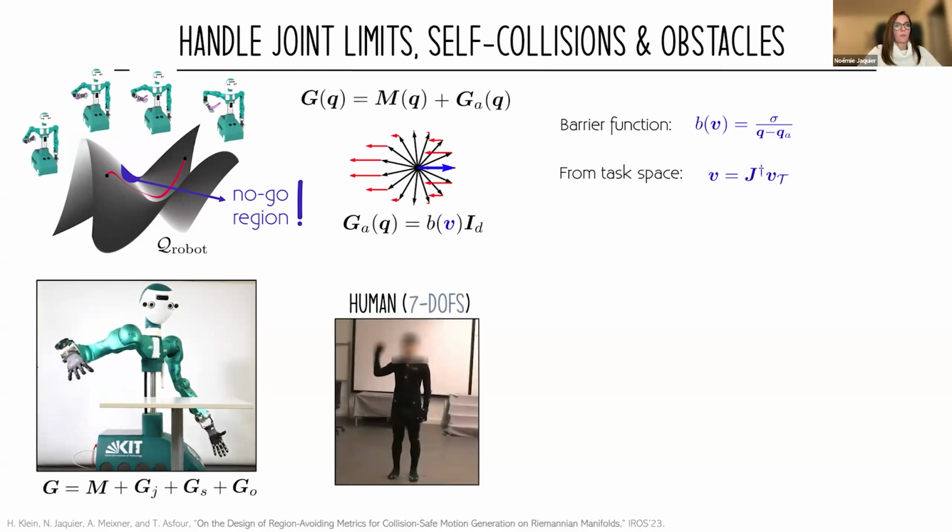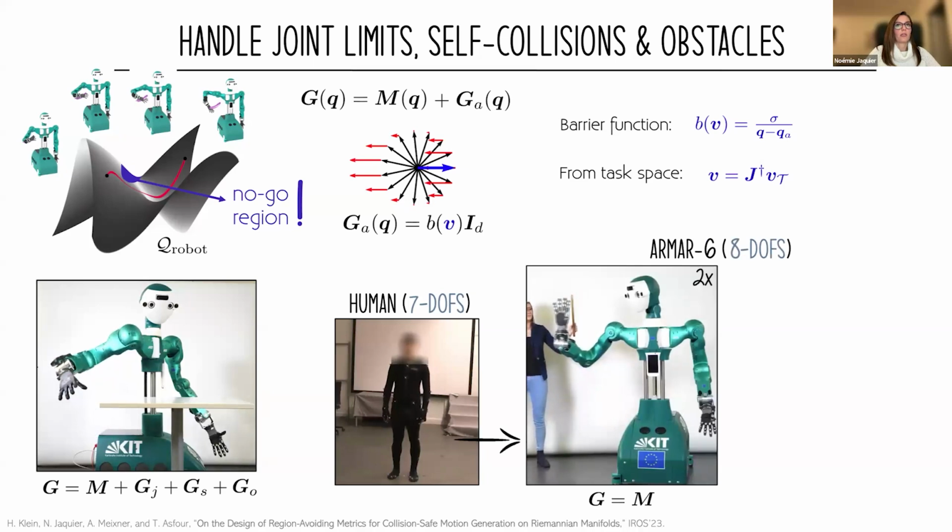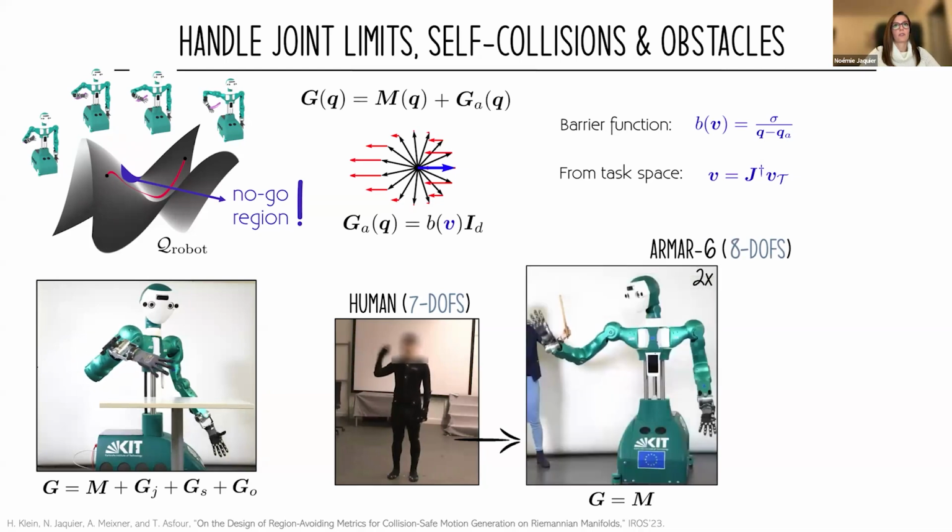We can also use this approach when we are transferring motion, following what I presented in the previous slide. Here we have a human motion, and here we are reproducing it with the robot, again as a sequence of synergies of geodesics, which is adapted to the robot at hand. Here you see that this is really just the geodesic in the robot configuration space, and I'm putting an obstacle in the middle, and the robot, of course, doesn't avoid it.